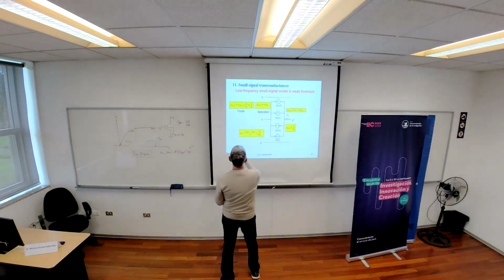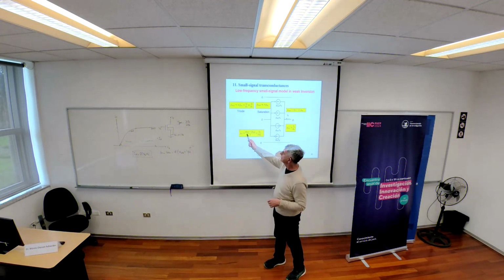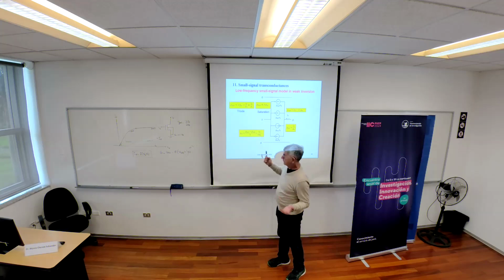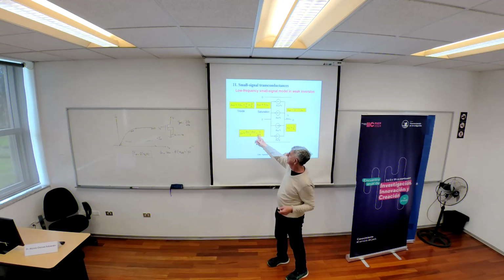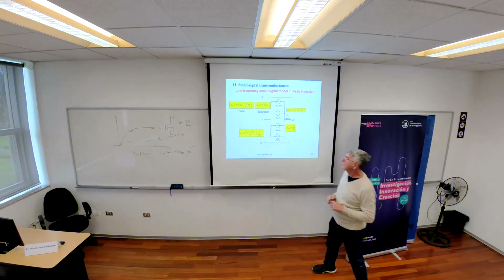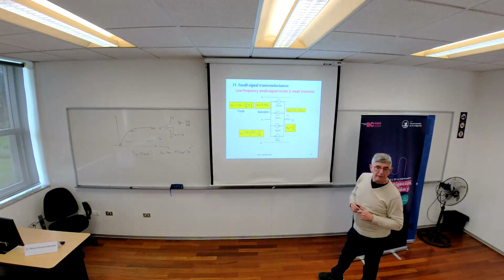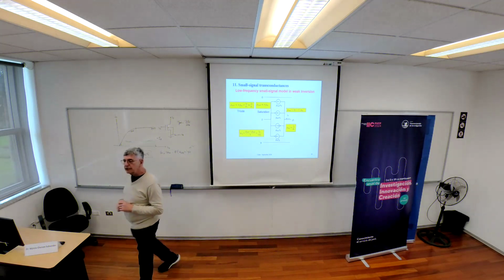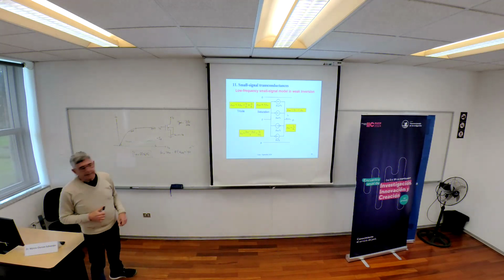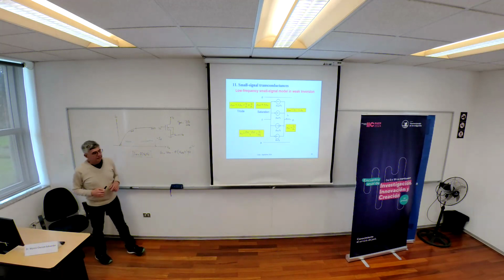All right. What's GM? GM is a combination of the source and drain transconductance. So in most of the cases, you can use just this relationship here. And in general, or in saturation, this coefficient is much greater than this one. But for the general case, you have this formula for calculating the transconductance. So look here. What happens when ID equals 0? ID equals 0, then GM is equal to 0.